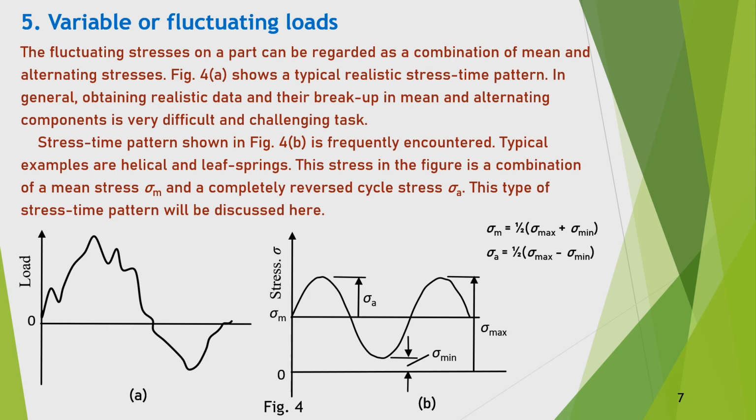It is important to learn how to deal with variable or fluctuating loads for fatigue design. The fluctuating stresses on a part can be regarded as a combination of mean and alternating stresses. Figure 4a shows a typical realistic stress time pattern. In general, obtaining realistic data and their breakup in mean and alternating components is very difficult and is a challenging